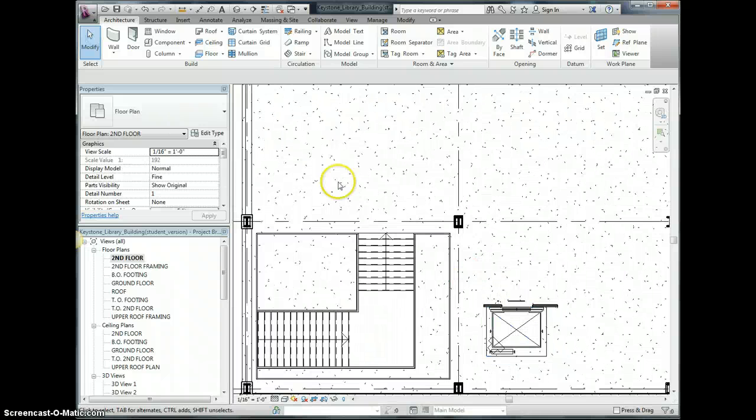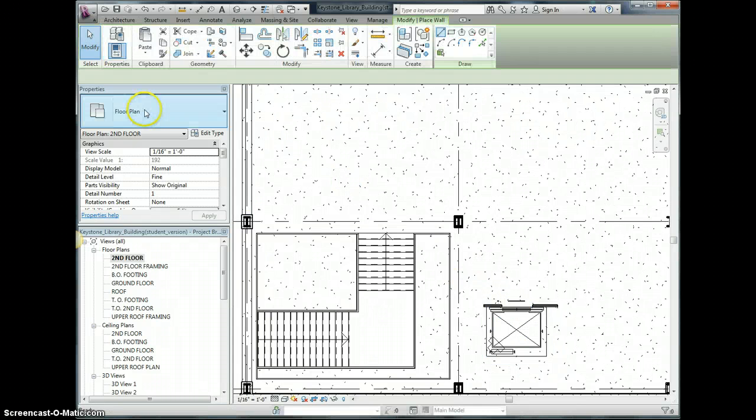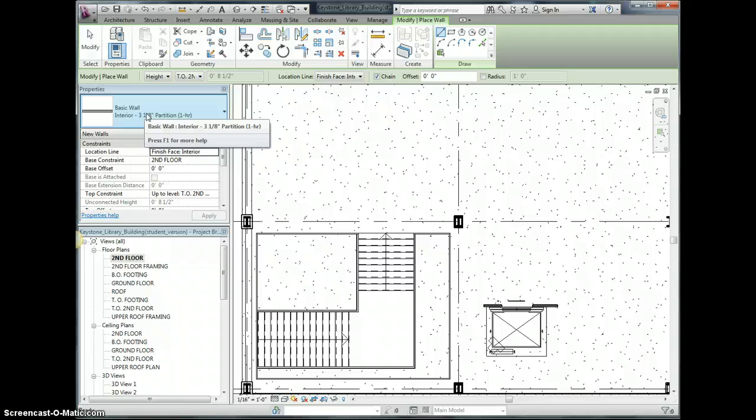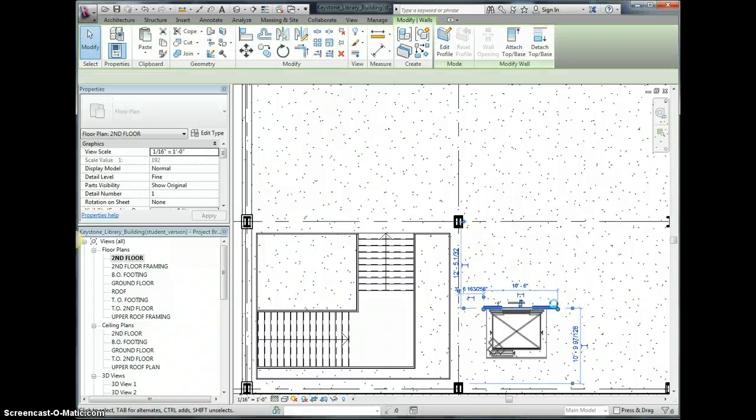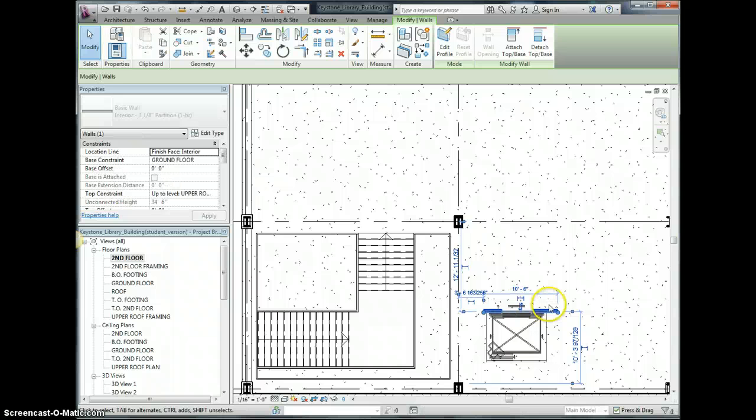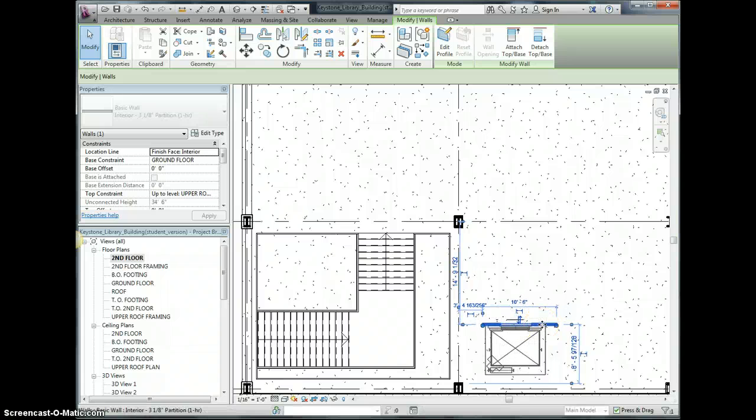Now at this point, you just need to place your walls and put this thing where you want it to go. If you move this wall here, so let's click Modify. If you move this wall here, it'll move this elevator, but it also will move the elevator on the other floor because they're both connected to that wall. So it works out quite well. So as long as I initially place it where it needs to go, then we should be in good shape.